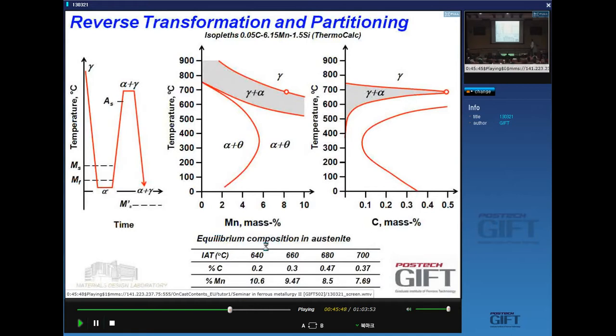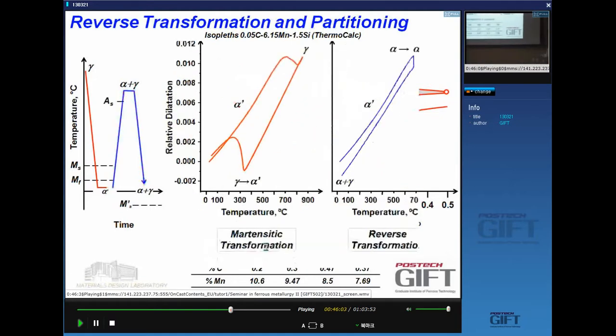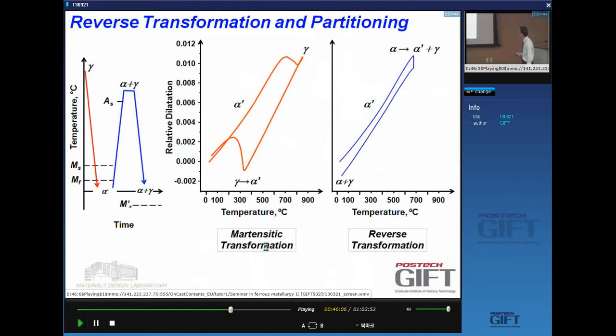And if you look at the composition of the austenite, the manganese composition is temperature dependent, and so is the carbon composition. And you see it peaks here to a very high value of 0.5. Yes? And depending on the temperature, you get different compositions and different types of stability. You can see by dilatometry, if you do the first cooling, you get, of course, a martensite transformation. If you do reheat, an intermediate anneal, and you cool back, that is here, and you cool down, there is no more martensite transformation. So you've stabilized the austenite.